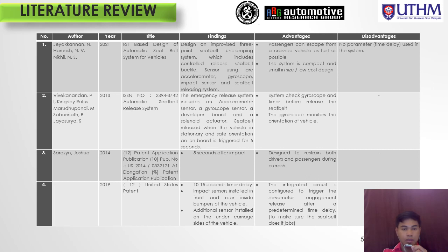The finding that I found in the thesis is that it designs and improvises a three-point seatbelt and clamping system, which includes a control relay, seatbelt buckle, and sensors using an accelerometer, gyroscope, impact sensor, and seatbelt releasing system. The advantage of the system is that passengers can escape from a crashed vehicle as fast as possible. Second, the system is compact, small in size, and low cost. The disadvantage of the system is that no parameter, which is time delay, is found in the system.